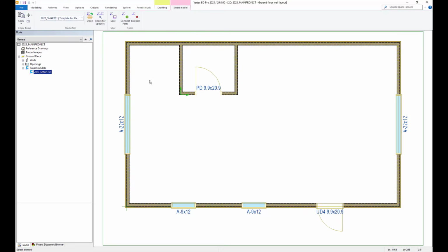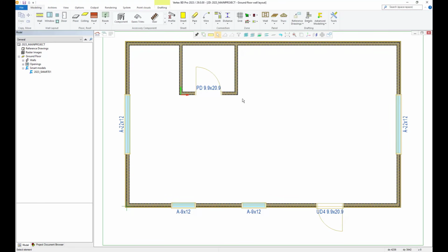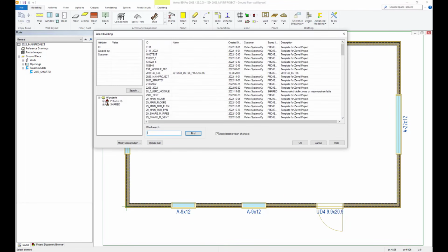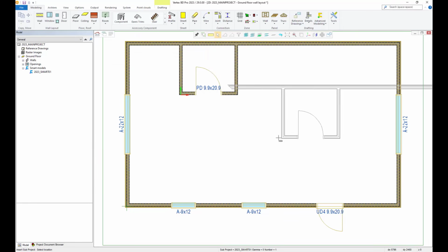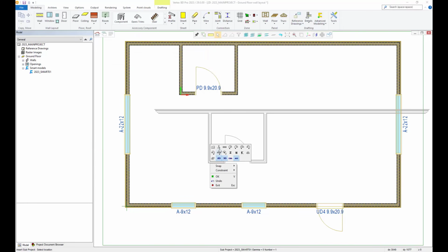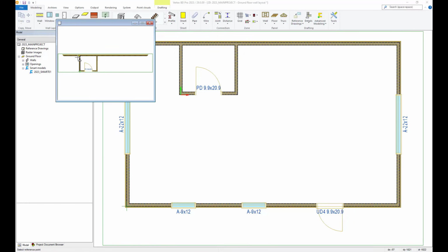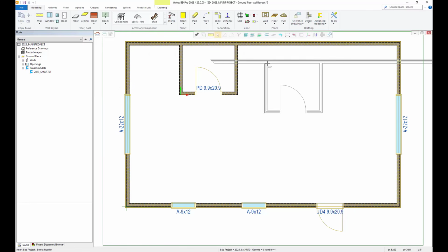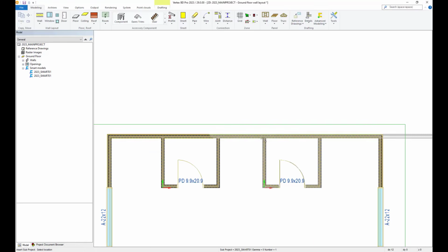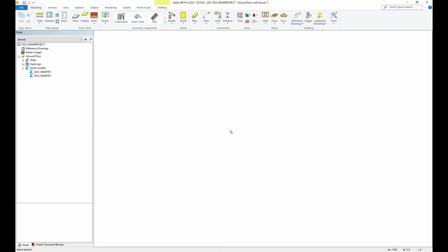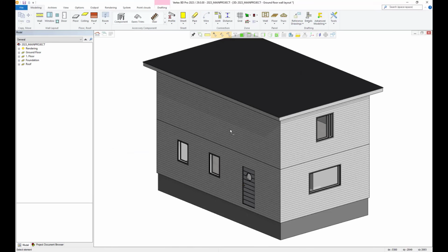Let's add another copy of our Smart Model to the existing project. Go to the Sub-Project drop-down as shown and select the Smart Model option from within here. Find and select the Smart Model as required, then select OK. Once selected, the Smart Model will be ready to place with predefined reference geometry. So we will change the reference point and add it to the project as shown. Now we have two of our Smart Models within our active project.